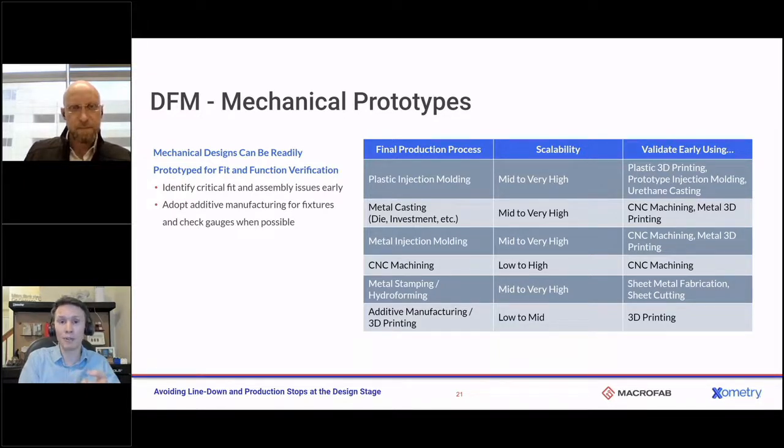And we also have metal additive processes that can help substitute, particularly for die cast and MIM components. For die cast and MIM, direct metal laser sintering, DMLS, 3D printing is a fantastic substitute, and honestly sometimes outperforms the die cast option in the end. But I love CNC because it's just like, looks like a duck, quacks like a duck. CNC machine it. We can scale with that.